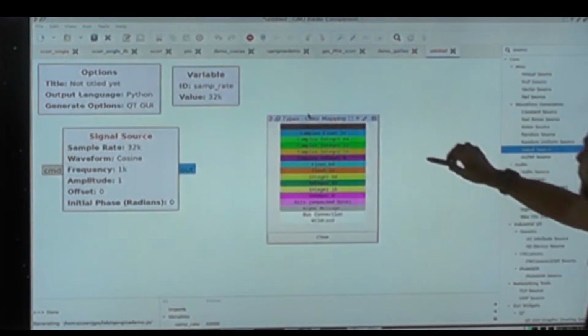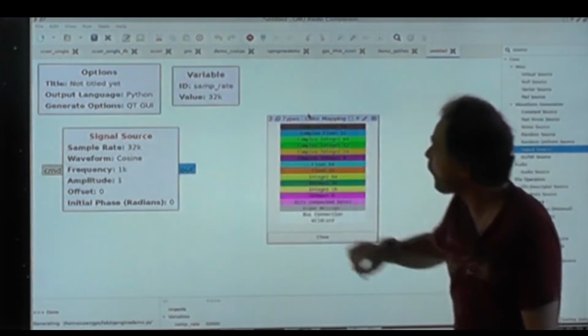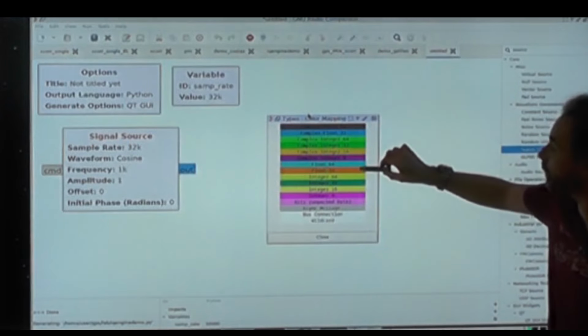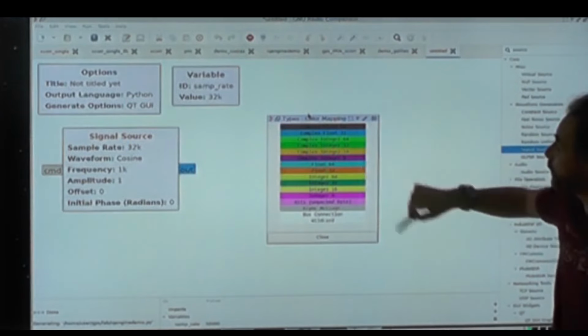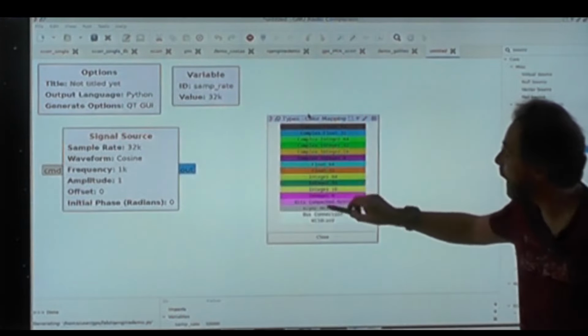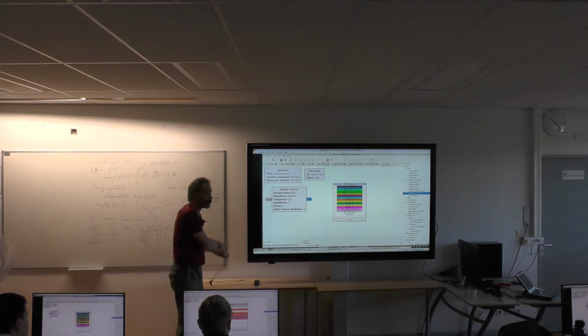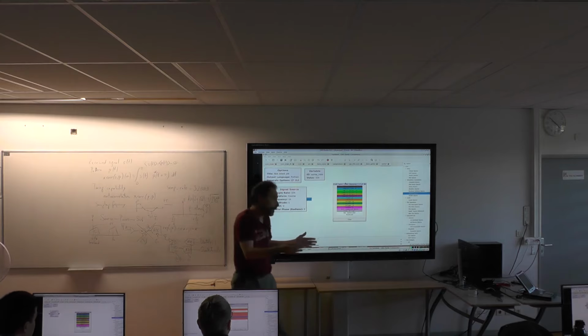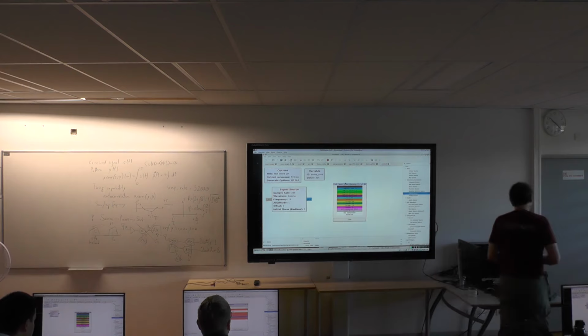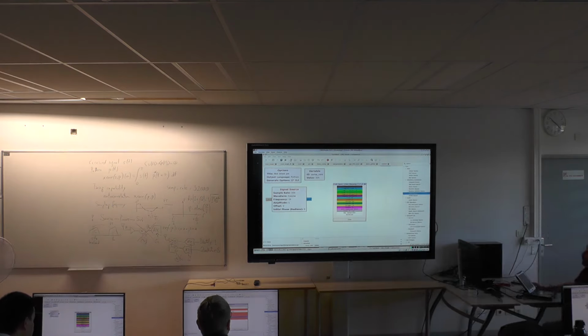You see that everything that is blue is complex quantity, real plus imaginary. Everything that is orange would be a real single precision floating point number. And before the end of this tutorial, we're going to see that we will manipulate integer 8-bit, because if you have a software-defined radio receiver that streams 8-bit outputs, it's natural to store in a file the 8-bit quantities and to stream in the flowchart these 8-bit values. Okay. So you see here you have a color coding of the value that is being streamed.